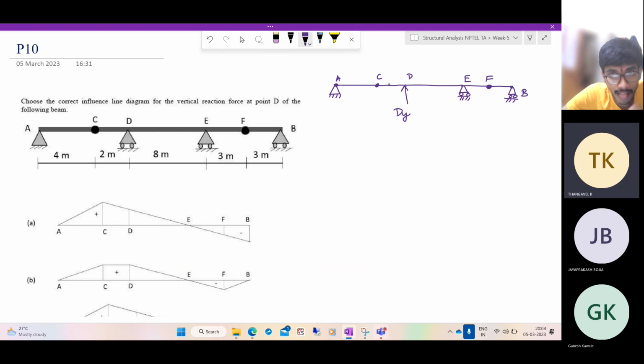So note that here we have not released any internal moment or the internal relative shear. So we have not released the internal relative displacement or the internal moment. So this unit will rotate as a rigid unit. So we have a hinge here. The region in between the hinge will rotate as a rigid unit, also obeying the other boundary conditions.